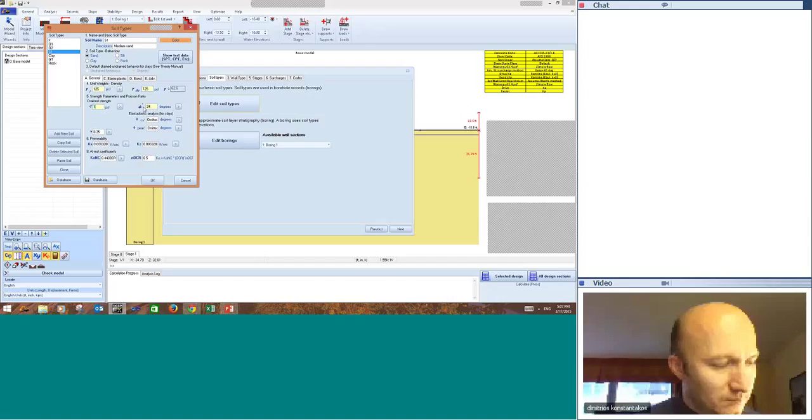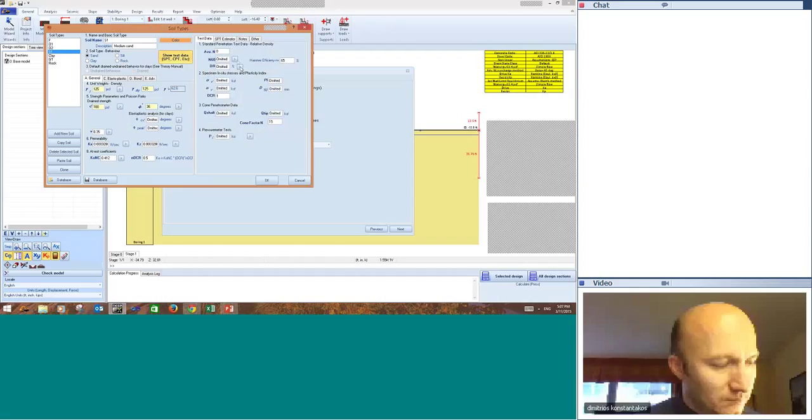And we're going to use 100 psi cohesion and 36 degrees friction angle. Now, there's also ways of estimating properties from SPT test data. There's recommendations here, anywhere that you see something like this. So we could, in fact, estimate the friction angle and other parameters from SPT. There's also a tool to drag the SPT values along like that and get a rough estimate.